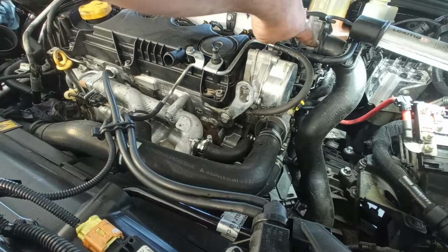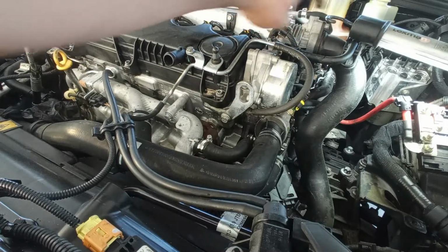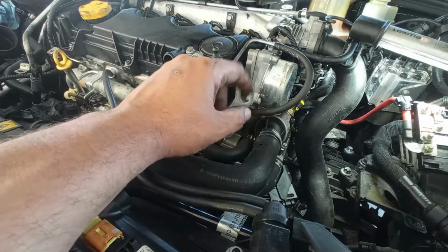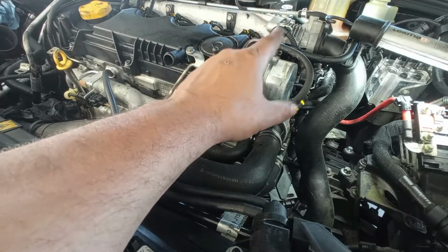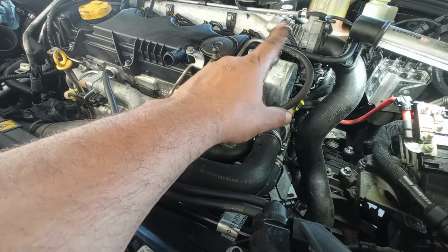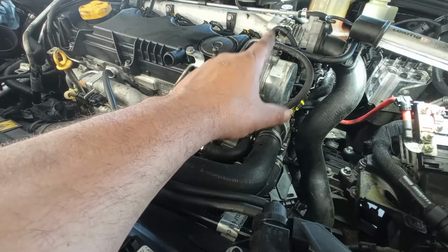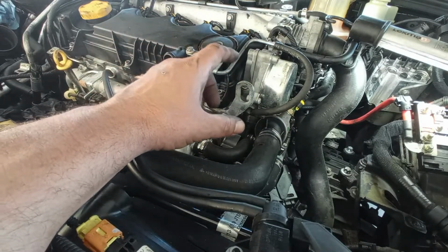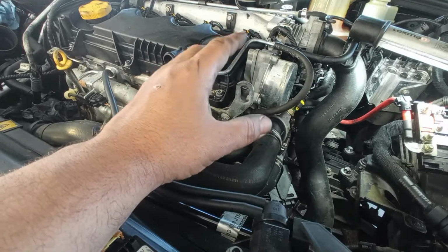I also have here a leak, a very large leak. I have an O-ring to put in. I already did that on another video, I can leave it down in the description. It was the video for the EGR. So I will take out that EGR, see if that gasket is really what it is supposed to be. I have a new one to put in. See if that EGR valve is not stuck open or closed. And work with that. A lot of things here to consider when dealing with DPF problems.